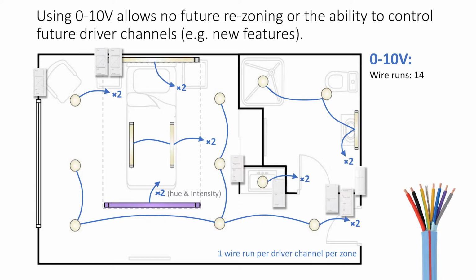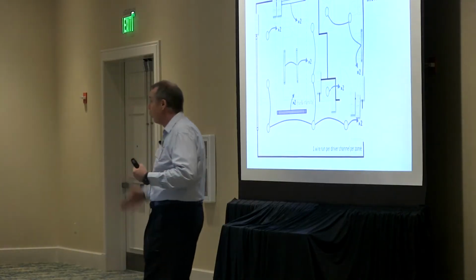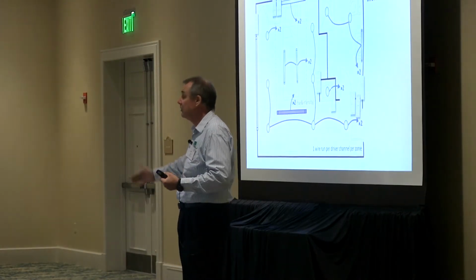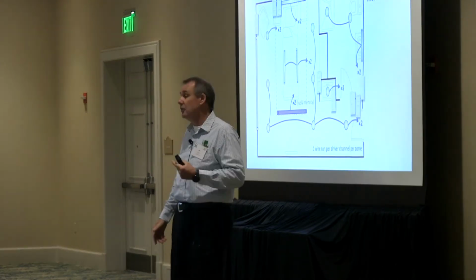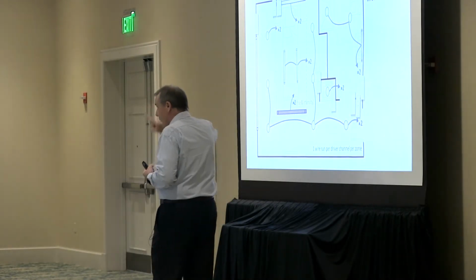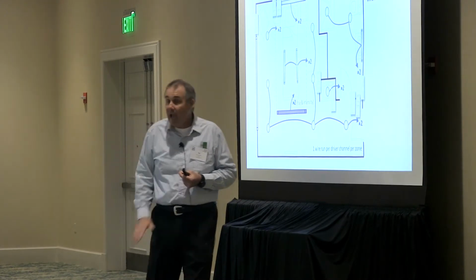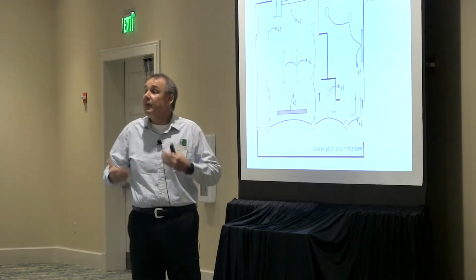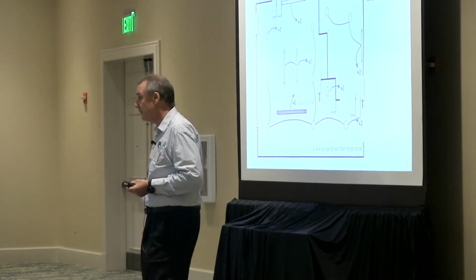The reason I tell you that is it's an analog method of control that is not defined by any standard of what the dimming level needs to be between 1 and 10 volts. It is also susceptible to long distance runs, voltage drop, and electrical interference. However, the fixture people are going to push this because this is what they push for dimming.